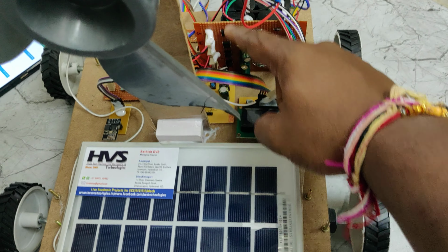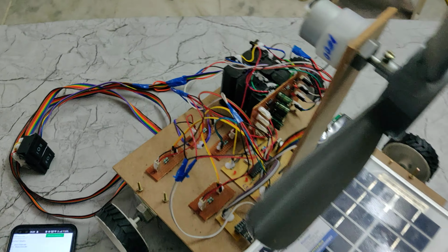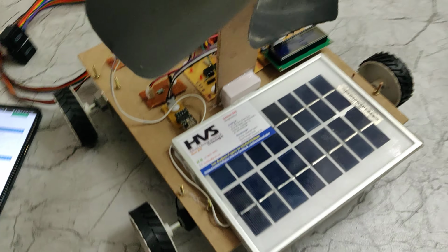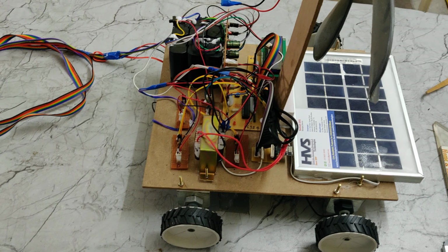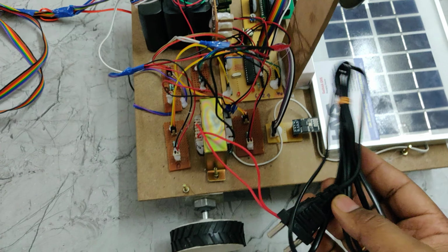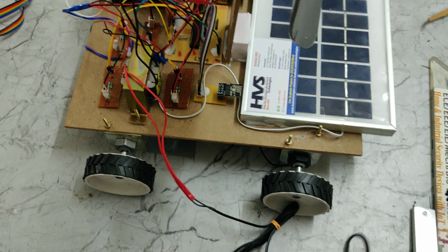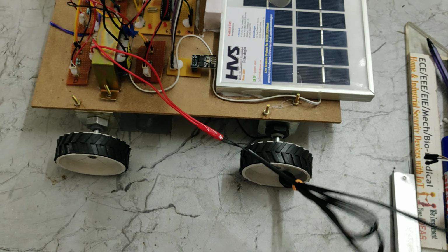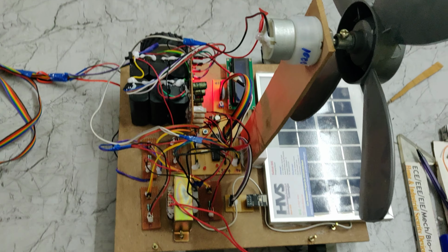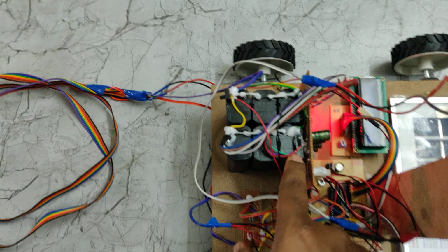So these 4 are: one for the solar, wind, dynamo, and there is a transformer. Whenever these 3 sources are not available, we make use of a transformer to charge the battery. With the help of this transformer we can charge a battery when the sunlight, wind or dynamo's power supply is not available. To charge the battery from this transformer, just turn on the power supply of 230 volts to this cable, then we can see the charge light indication on this charging circuitry. It will get fully charged in a minimum of 8 hours, maximum 12 hours, as we are using the battery pack of 12 volts 2 amp.